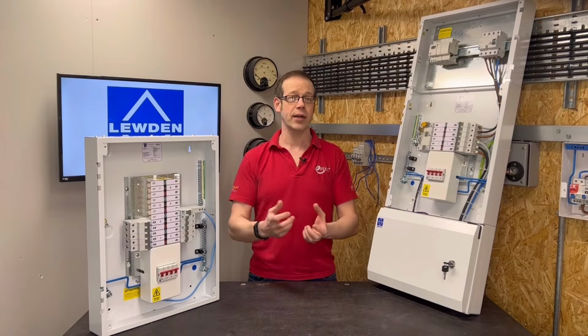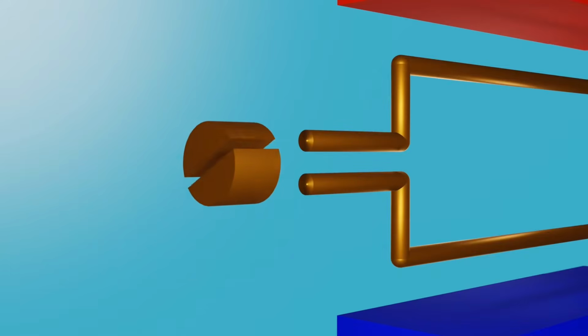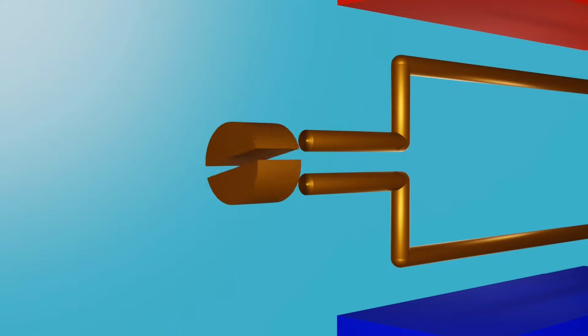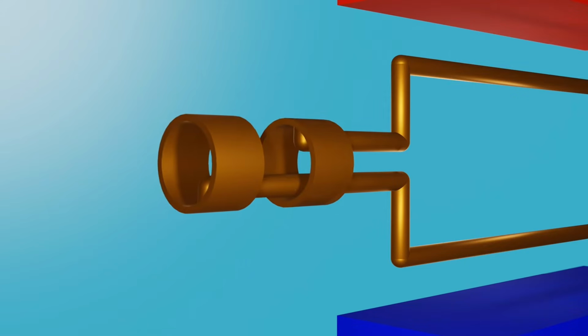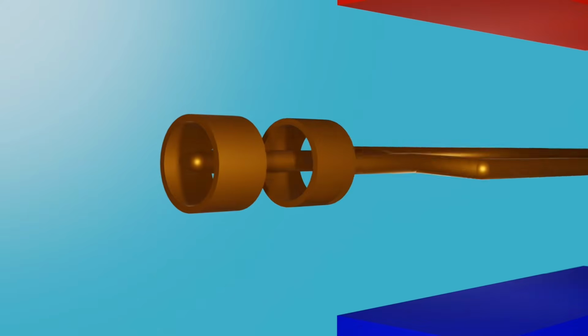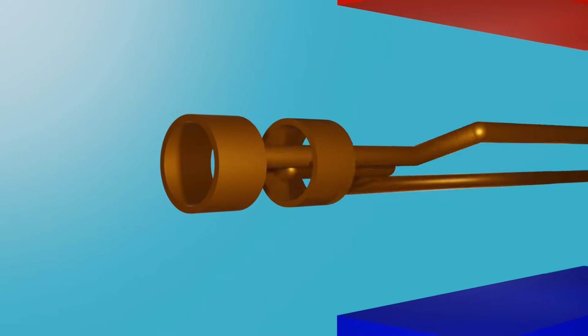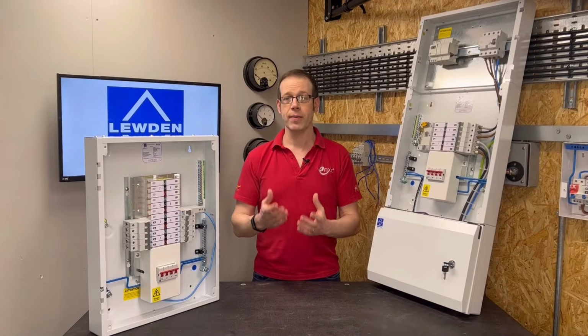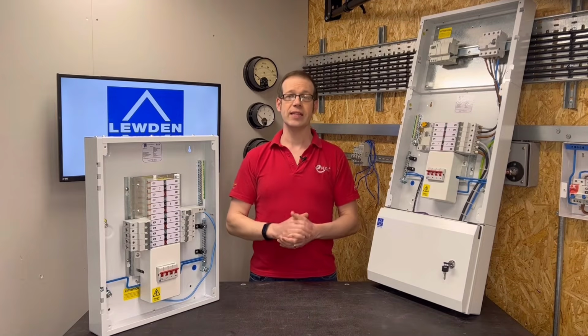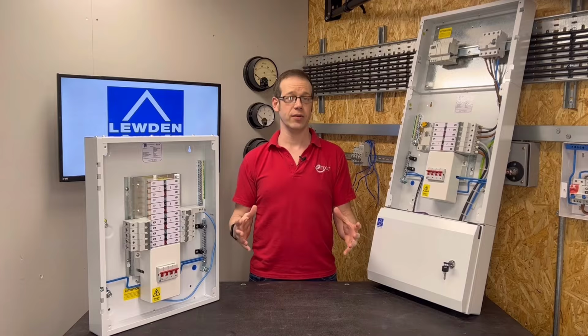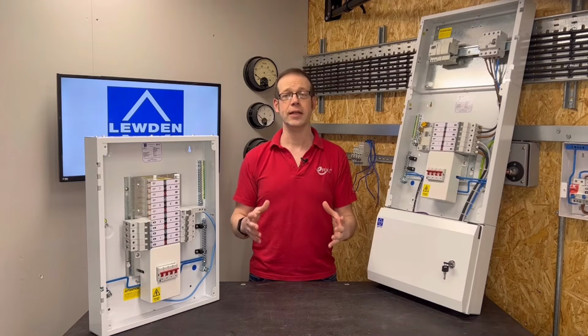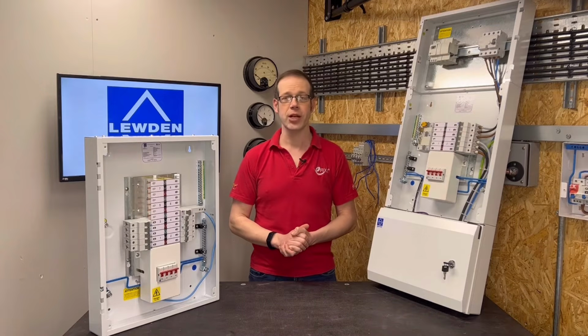Depending on how we extract this electricity, we get either DC using what's called a commutator or AC by using slip rings. To make a practical generator that will generate enough electricity to be useful, we don't just have a single loop of conductor, but rather we wrap the conductor round many times, turning it into a coil. This effectively increases the length of the conductor cutting through the magnetic field, which increases the EMF from the generator.